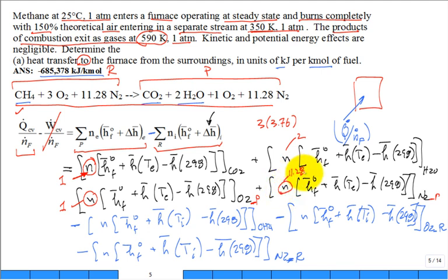And the stoichiometric coefficient of the nitrogen in the products: 11.28. All right, stoichiometric coefficient of the methane in the reactants. Well, this one's easy. We like to leave a 1 in front of the fuel. It's very, very rare not to. In this case, the fuel is methane. Stoichiometric coefficient for the oxygen in the reactants: 3. See, this is confusing. They say, hey, we already did the coefficient for oxygen. Yeah, but this time it's in the reactants. Okay, and then nitrogen. Nitrogen is not undergoing a reaction, so it came in 11.28. Stoichiometric coefficient goes out 11.28.